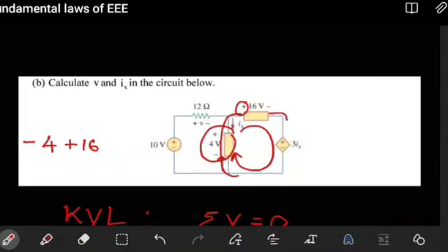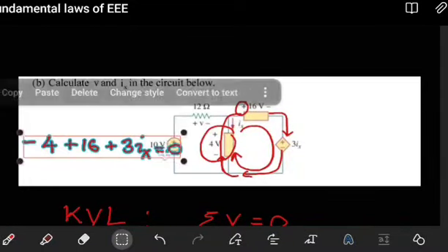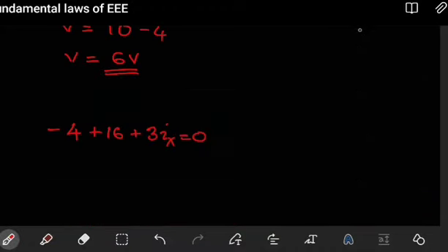When we continue, we now find this dependent voltage source, and we find it positive first, so we have plus here, and this is going to be plus 3Ix. So this has to equal 0. That is the last circuit element in that loop. You see that everything else is known except Ix, so you can work this out to find Ix.